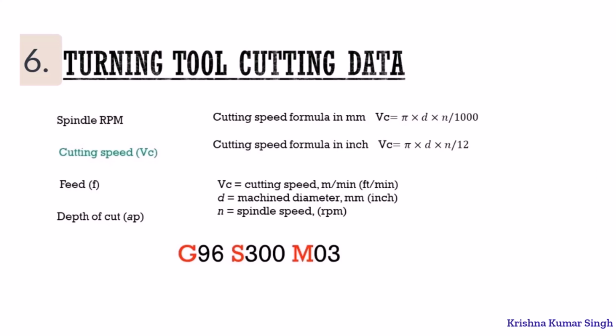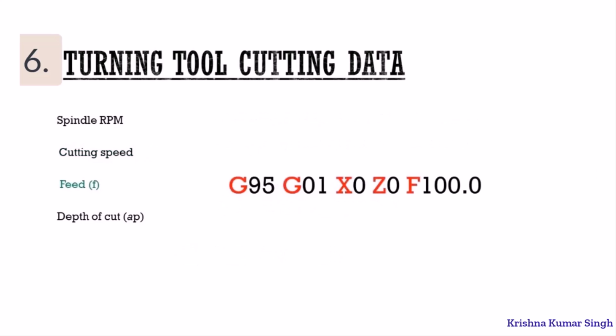Since it is constant cutting speed, when the diameter where the tool contacts the workpiece decreases, the CNC machine increases spindle RPM, and when the diameter increases, it decreases the RPM. This way, the cutting speed stays constant, resulting in a uniform surface finish for both small and large diameters. Like RPM, if the cutting speed is higher, the surface finish is better, but this might result in excessive tool wear.